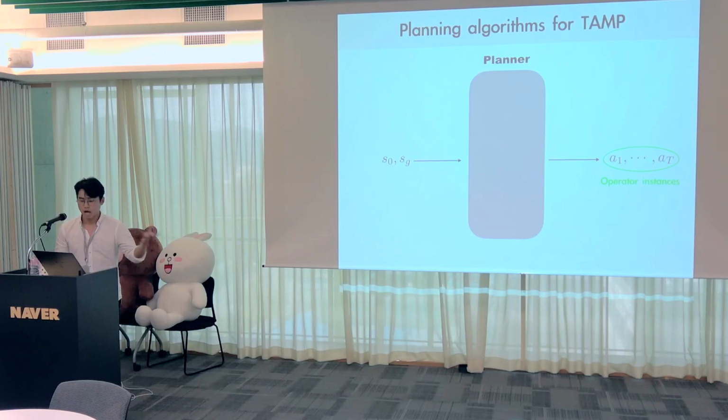For example, for the pick operator, we had to define object O, base pose, and a grasp, and that completely specifies an instance of an operator. Associated with each of these operator instances is a sequence of robot configurations that actually achieves the robot motion. This sequence of configurations might be a pick motion for picking up the object.